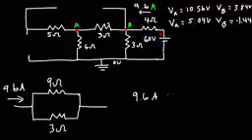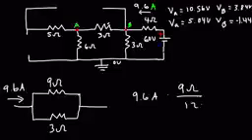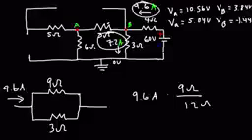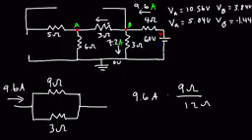It's going to be 9.6 amps times the other resistor divided by the sum of them. So it's 9.6 times 9 over 12. Thus we get 7.2 amps flowing through the 3 ohm resistor. And 9.6 minus 7.2, that's 2.4. So we have 2.4 amps flowing towards point A, and also flowing through the 6 ohm resistor.